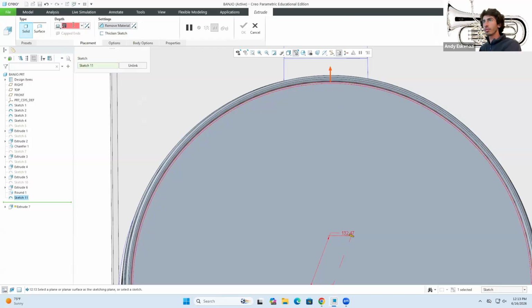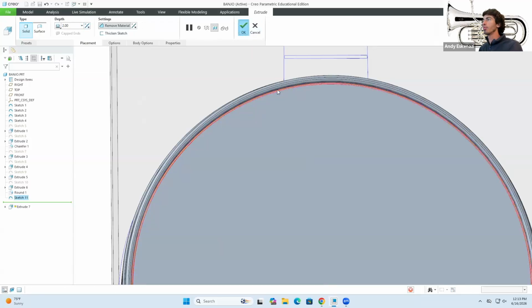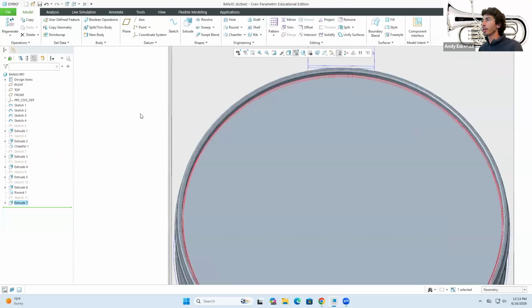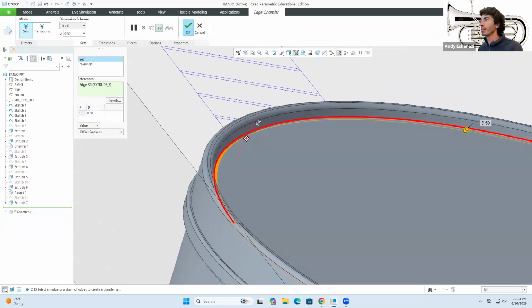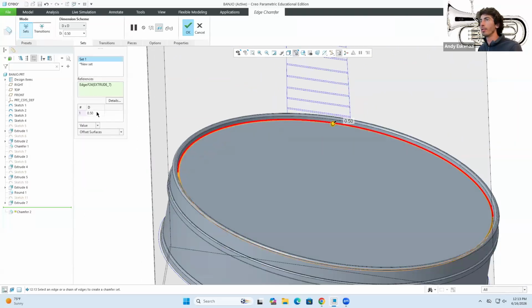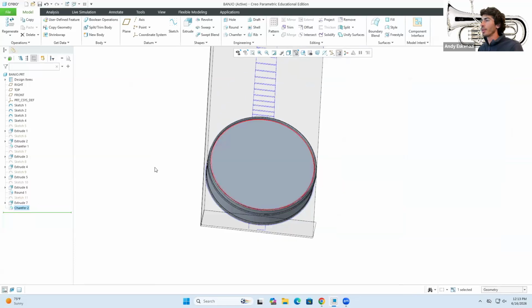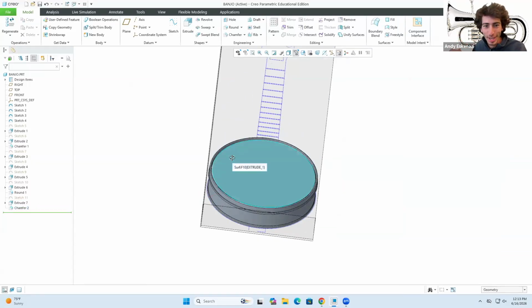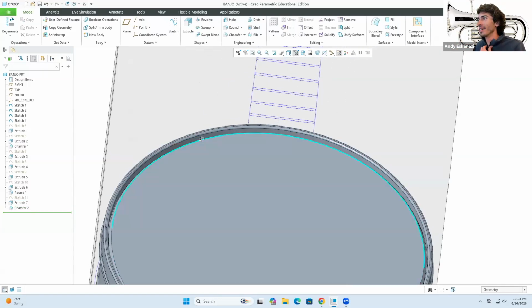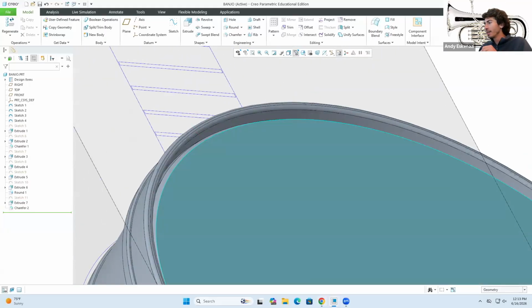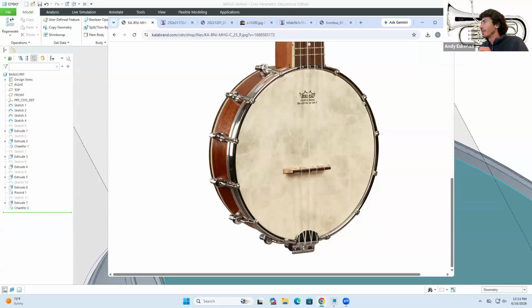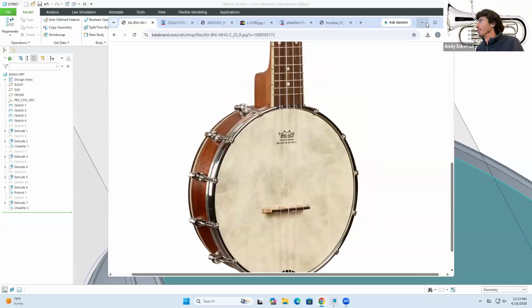Okay. We remove material. There we go. Good. The reason why we did that is because now I'm gonna chamfer that just like we did before, let's say with a 1. This technique that we're doing here, by the way, kind of looks like the top side of a Coke can. If you've ever seen some of my videos designing that, there you're leaving just a tiny bit of gap that you can kind of see in there.